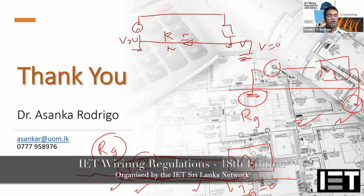You cannot avoid that part because, due to the insulation capacitance, there is always a leakage current, but you can estimate that part. As a designer, depending on the list of equipment, the list of cables and their cable lengths, you can estimate what the leakage value is, and you can set your residual current protective device's leakage current a little bit higher than that value.